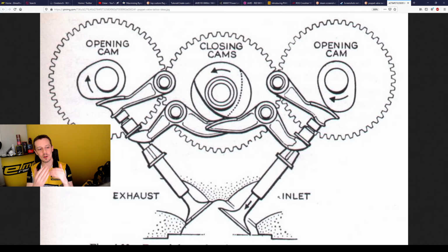But then you need to be able to close the valve also. So Desmodromic systems have a separate camshaft to push that closed. And this of course works. So you would think that then you don't have resonance frequency problems and mass inertia problems as much as with coil spring type valves, but that's maybe not entirely accurate, because I'm assuming you can probably make these Desmodromic systems capable of running to extremely high RPM, but there is a big problem with these.